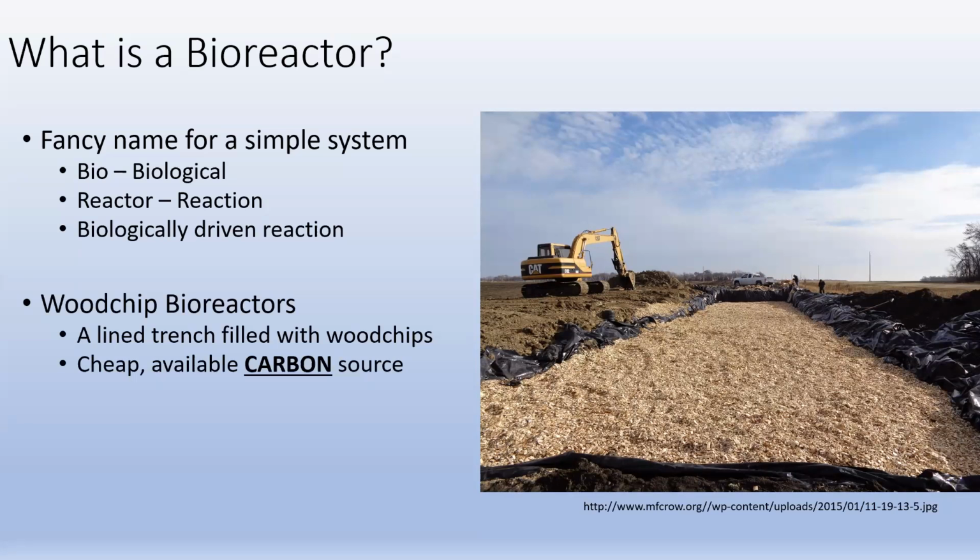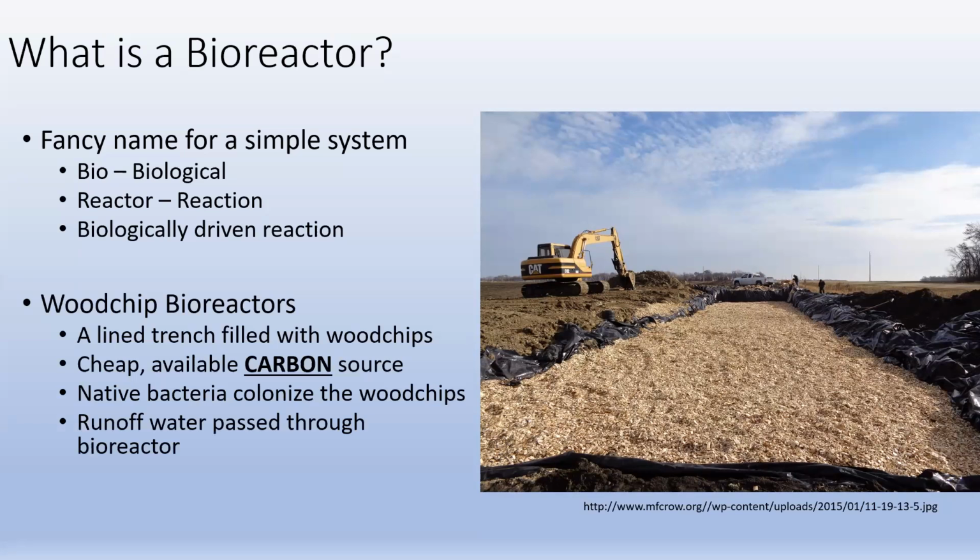Most importantly, it's carbon. And then on these wood chips, native bacteria colonize these wood chips. So the bacteria already existing, bacteria need carbon, right? You're just giving them a full feast right there. So they're going to colonize these wood chips. And then what happens is runoff water is going to be passed through these bioreactors. And that way, as it goes through, the bacteria are going to do their treatment on them.